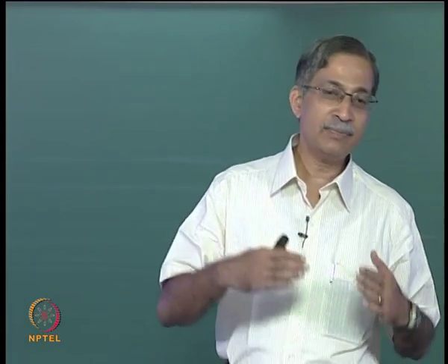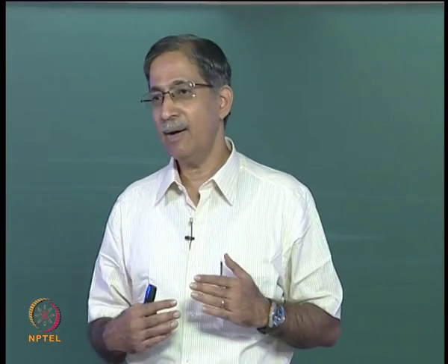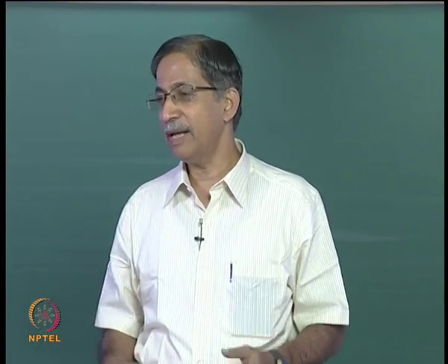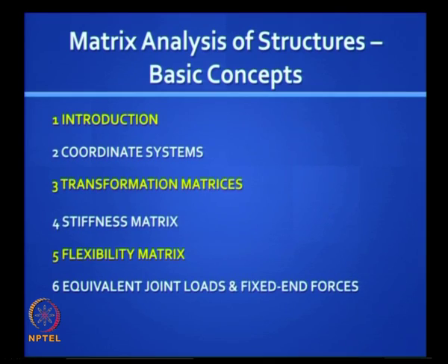So similarly in a structure, the members can have their independence, but unless they operate together harmoniously in the interest of the overall structure, you will have problems. So similarly you have to understand stiffness matrices and flexibility matrices both at the element level and how it all fits in at the structure level. And you have already studied this. Whenever you encounter intermediate loads, because you want to limit your degrees of freedom, you have to pass them effectively to the joints, so you need equivalent joint loads and you need to find fixed end forces.